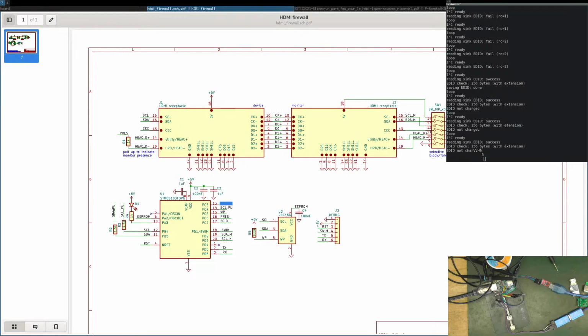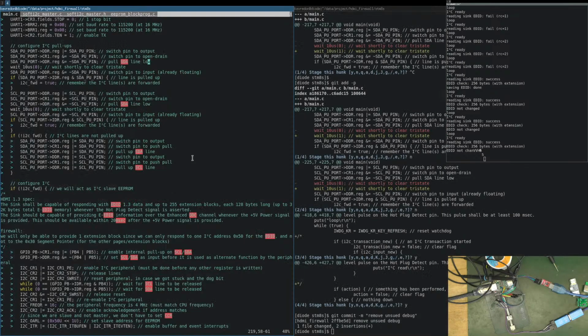That would be the proper way because I don't know if it's pulled up fast. Yeah, high, low, high. Although high, low is good enough. The problem is if the source, so the real device, also pulls it low within these 20 milliseconds. If I do high, low, high to verify and it pulls it low, then it won't work. So let's just do a high and low and not just high, because high we see it doesn't work.